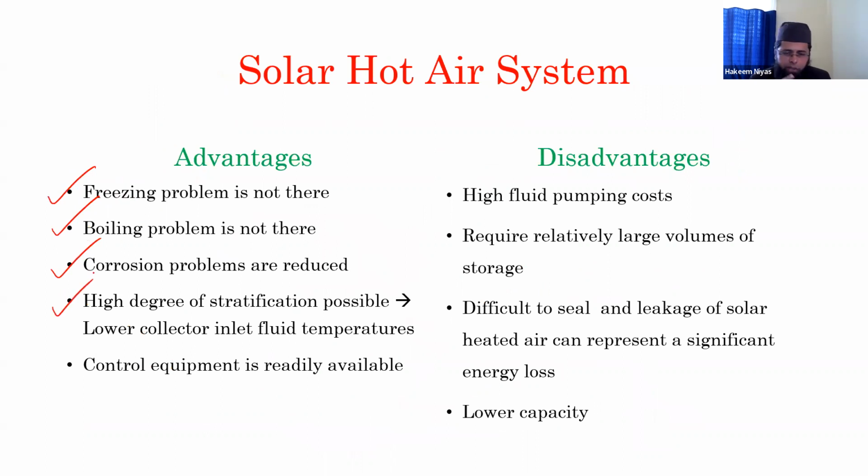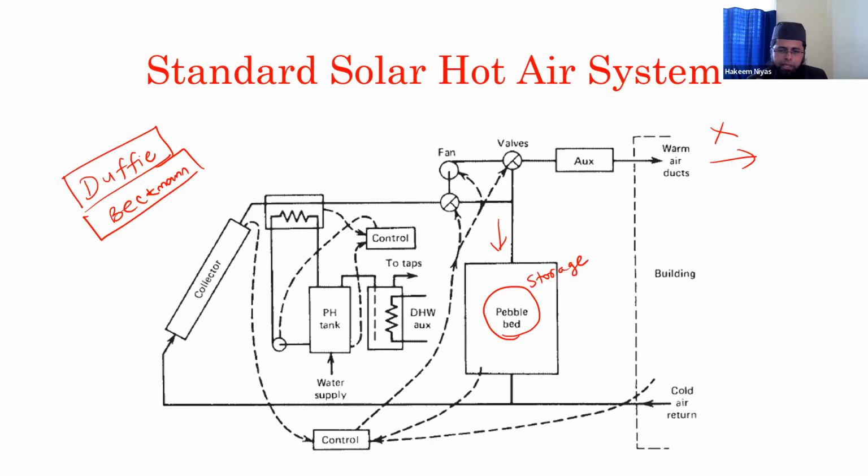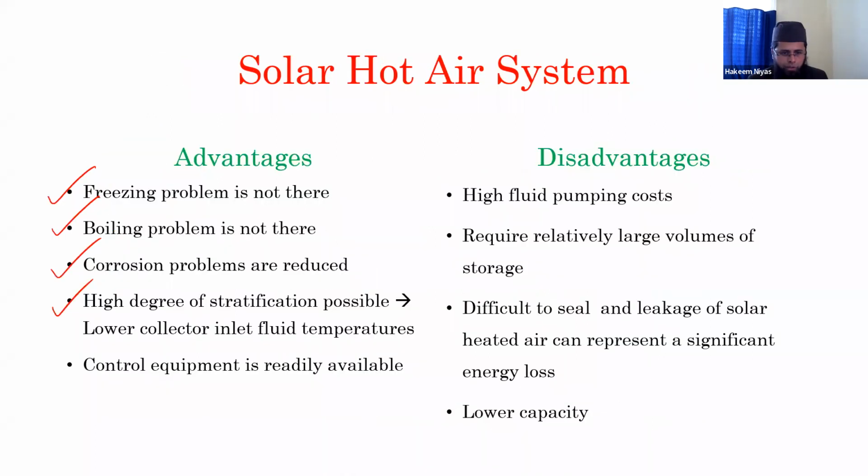A high degree of stratification is possible, which means that as the specific heat of air is low and its density is also low, the starting region will have a high temperature and the end region a low temperature. The difference in temperature across layers is huge.